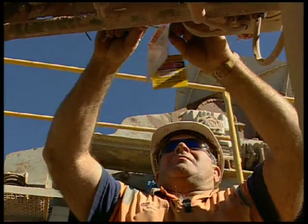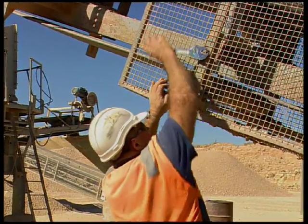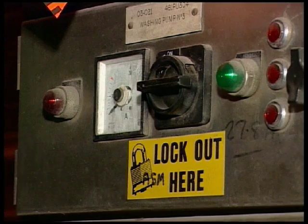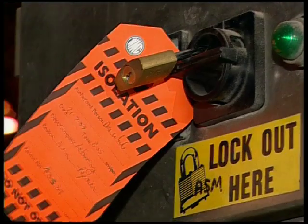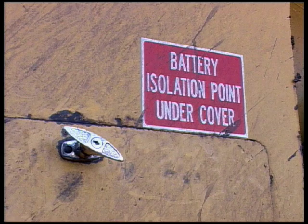A good lockout isolation procedure ensures that plant is unable to be turned on while an employee is working on it. An energy isolation point is the physical point where plant is safely isolated from energy sources. All energy isolation points should be uniquely and permanently labelled to indicate their function for isolation purposes.